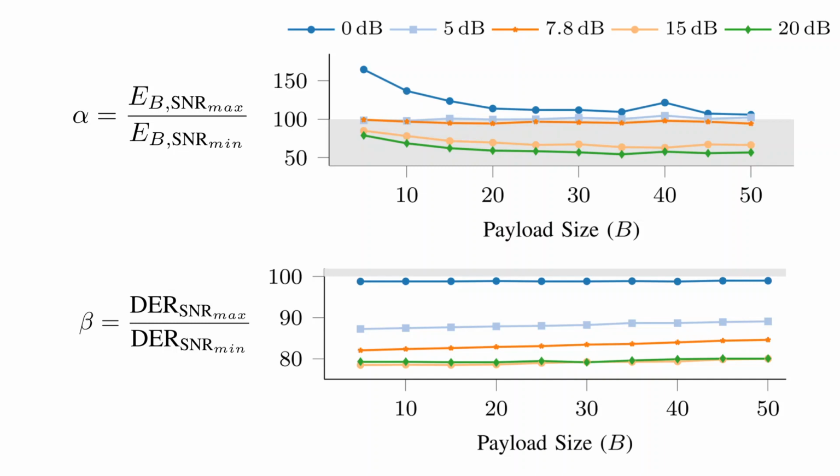For the data extraction rate, it's always better to underestimate the channel, which is logical, as you send with a higher transmit power or a higher spreading factor, and thus the gateway is able to receive your message better. So choosing between SNR max and SNR min allows for making a trade-off between energy efficiency and effective throughput.